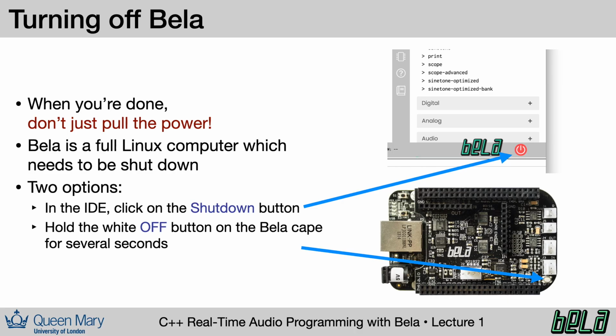Finally, when you're done, don't just pull the power. Remember to shut down the board gracefully using either the power button in the IDE or holding down the white button on the Bela cape. This is so you don't lose any data when you shut down.